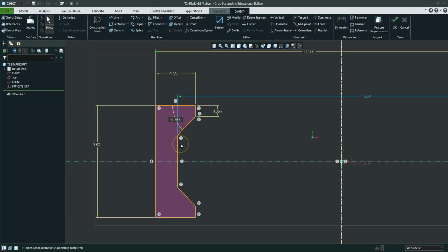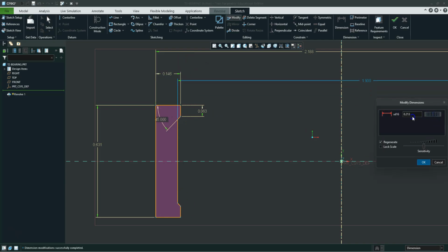All right. Now, once you use Creo more and you're more experienced with it, I've used it for years, I can kind of tell what it's going to do, which is sort of why I'm doing it in this order, to show how we get around it. But if you have a good handle on how your sketch is created and how your constraints are controlling it, it's a little bit easier to identify how the sketch is going to react when you change a dimension. But you can see what's happening with this one is as it shrinks in, it gets too small. It wants to keep that 45-degree angle and that height, but the inside line is the one that's not controlled right now.